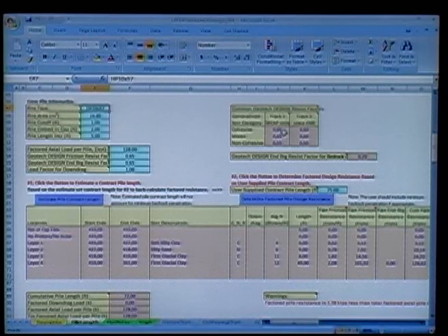So I'm just going to give you the values here so you don't have to go look them up. They'll be right there for the different soil types. And in this case, it was cohesive. We're doing a WEAP only, so it's 0.65. And if we had end bearing that was not rock, we could also use 0.65 on the end bearing. If we have rock, for bedrock, I list the 0.7 here, so you would put that in there if you were going down to rock. I've got the load factor for down drag, which is 1. I'm going to zoom down a little more.